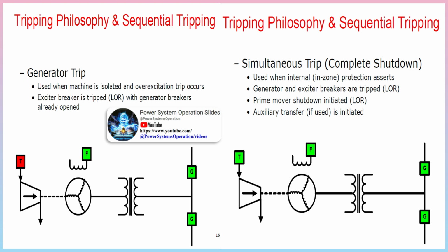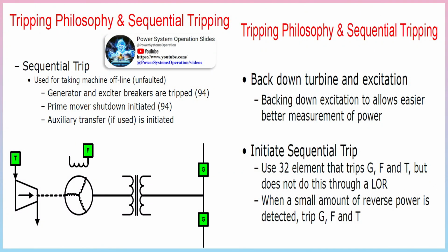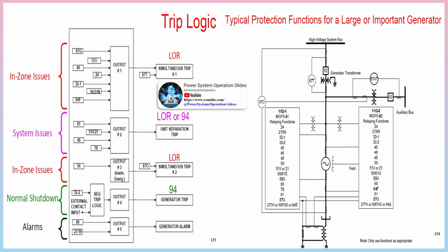Protection against vibration. Vibration detectors are usually mounted on the bearing pedestals. The detector consists of a coil mounted on springs between U-shaped permanent magnets. The voltage output from the coil, which is proportional to the degree of vibration, is passed from the coil into integrating circuits and then into an indicating instrument.